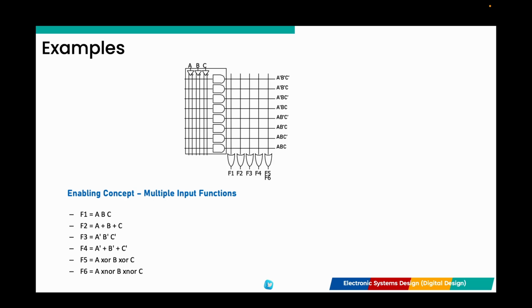Exclusive OR and exclusive NOR require multiple product terms. This means the number of AND gates becomes a limitation. The number of OR inputs also limits what we can implement. So, even though PLA is flexible, it is still constrained by a fixed number of product terms, limited scalability, and increasing complexity for larger designs. So how do we proceed from here?